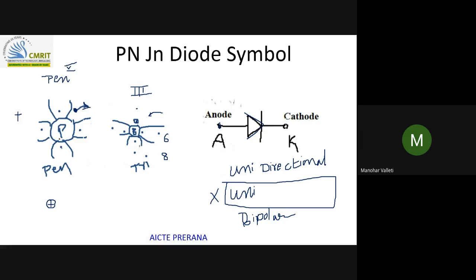That's why wherever pentavalent impurities are used, in whichever material, the atom is represented with a plus sign with a detached electron. In the same way, wherever trivalent impurities we use, as it is taking an extra electron, the number of electrons becomes more, so the atom becomes electrically charged, negative, with a vacancy of hole. Like that we will represent.